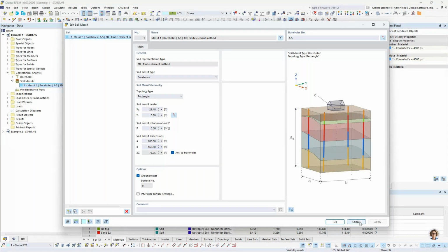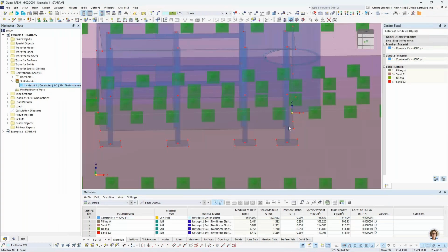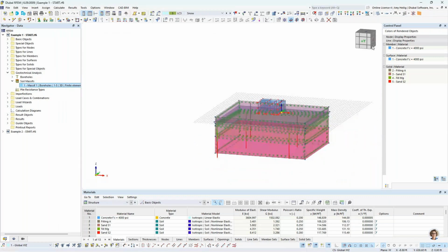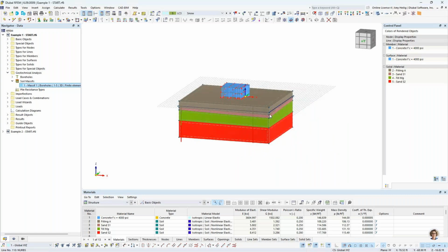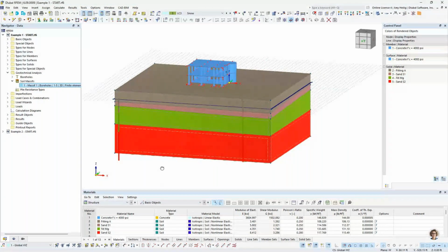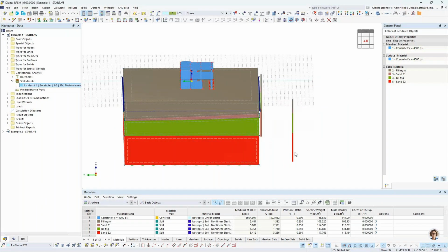When that is finished, I will go ahead and display the 3D solid, because I currently have it hidden. If I turn this into a solid rendered view, we get a nice look here at all of the different materials that were generated with the soil solid from the input of the boreholes. Now, notice that some of these boreholes exist outside of the solid, no problem.